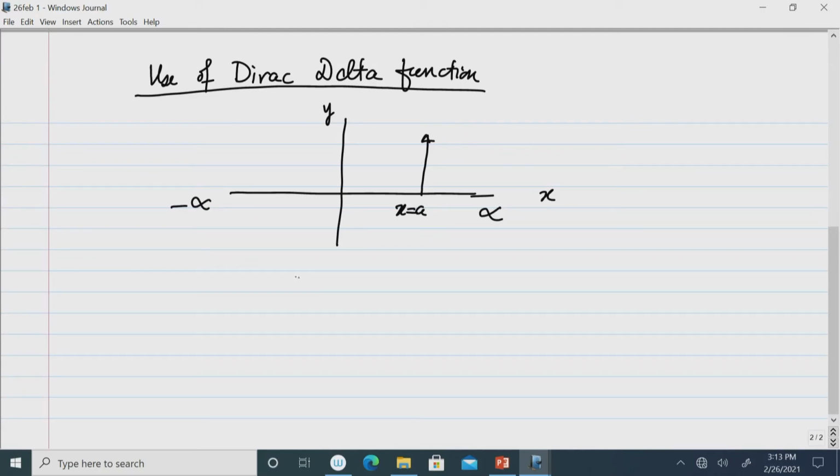So, that means this type of impulse function can be defined by a Dirac delta function which has the significance here, x minus a is 0 for x not equal to a, but at x equal to a, it still remains undefined and the magnitude is very high. But restricting this limitation, we will now use this Dirac delta function to represent the concentrated